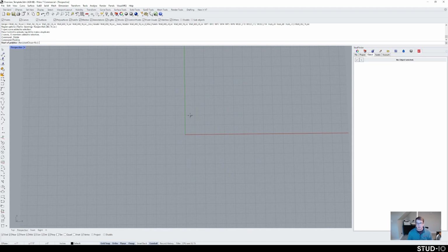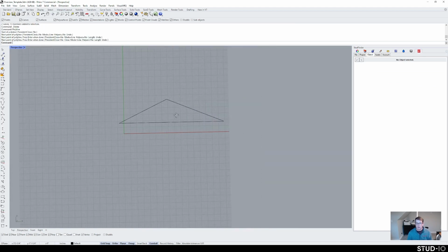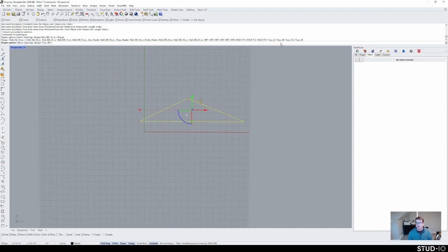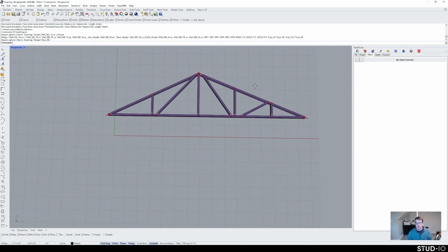One panel at a time is still pretty powerful. So real quick, let's say I want to build some roof trusses for a house. SF create region. We can use a truss 48 inches on center region. That will generate that for us.